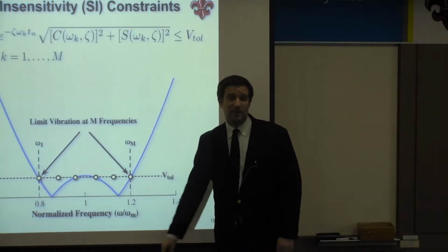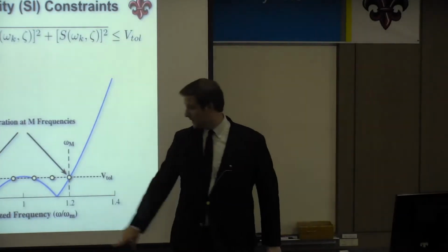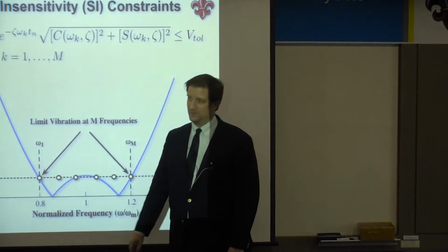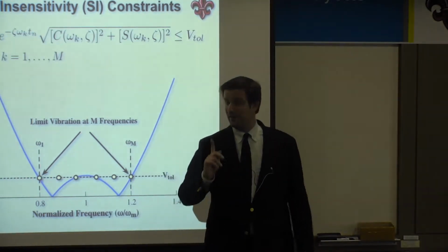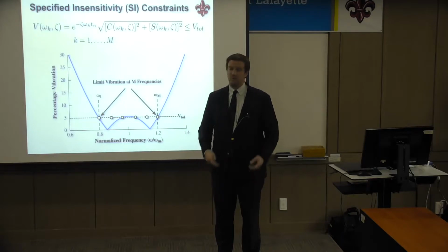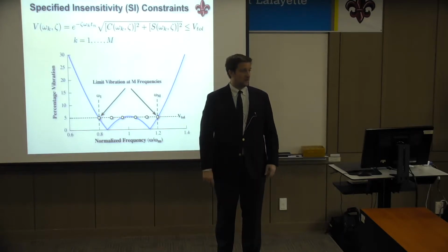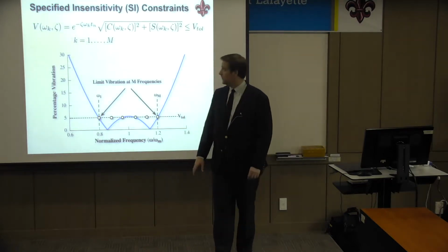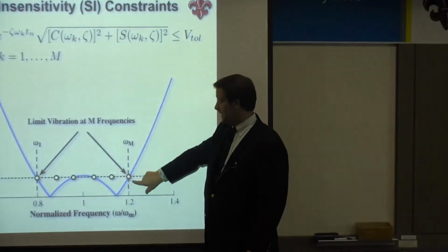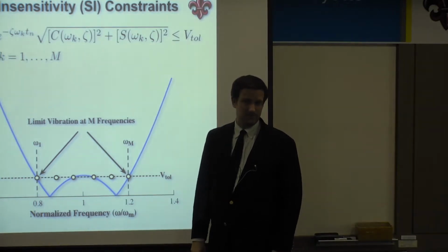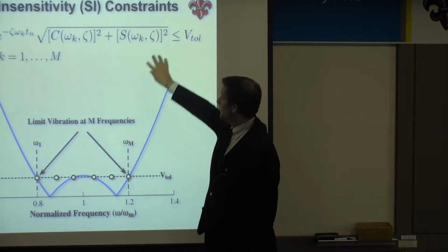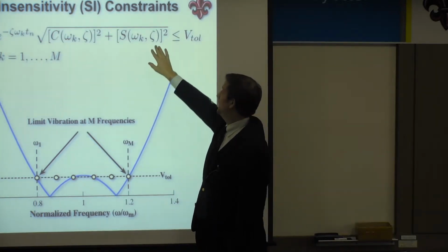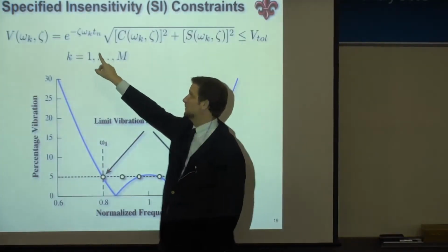And rather than limit the vibration just at one point, limit the vibration at m different points in this curve. So far we looked at limiting vibration only at one frequency, and the robustness, the insensitivity we got was just kind of an accident in some ways. In this case, we're specifying the insensitivity directly. So I take this vibration equation, the one we just solved, and so far we've been solving just for one frequency. And I solve it for m different frequencies, natural frequencies.